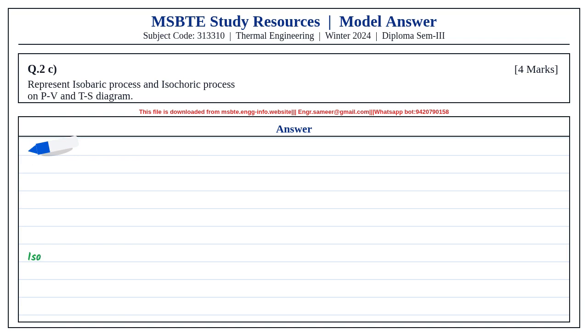0.293. Mass is PV1 divided by RT1 equal to 3.608 kg. At constant pressure, T2 by T1 is equal to V2 by V1, so T2 is 1135.2 Kelvin. Work done is P into V2 minus V1 equal to 700 kJ. Increase in internal energy is mCv into T2 minus T1 equal to 1701 kJ.